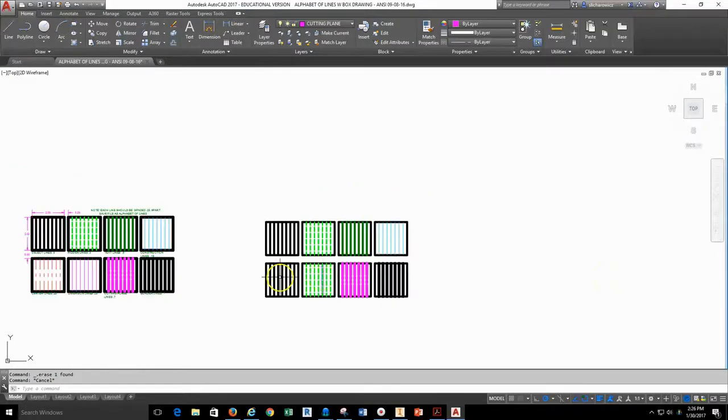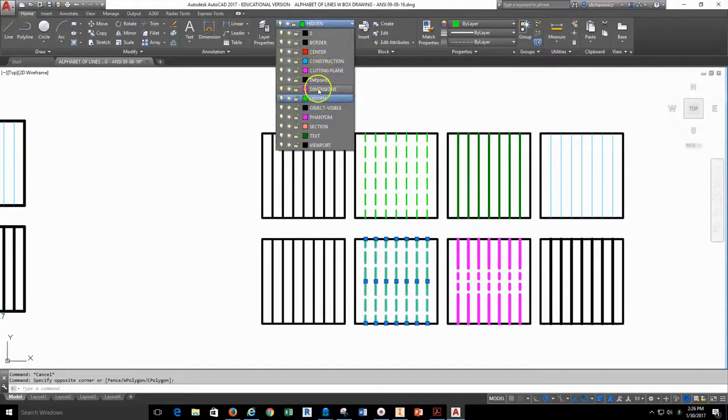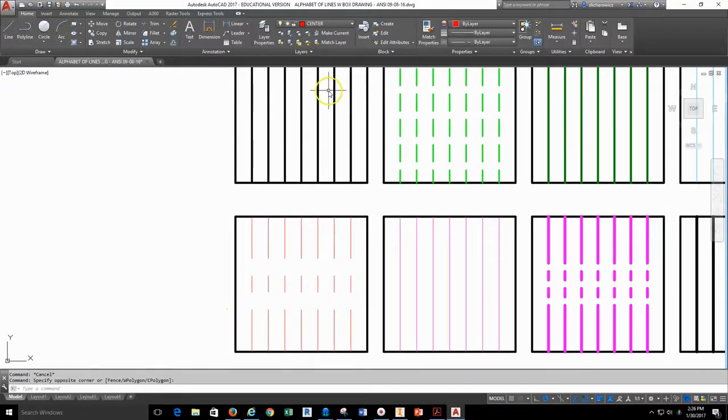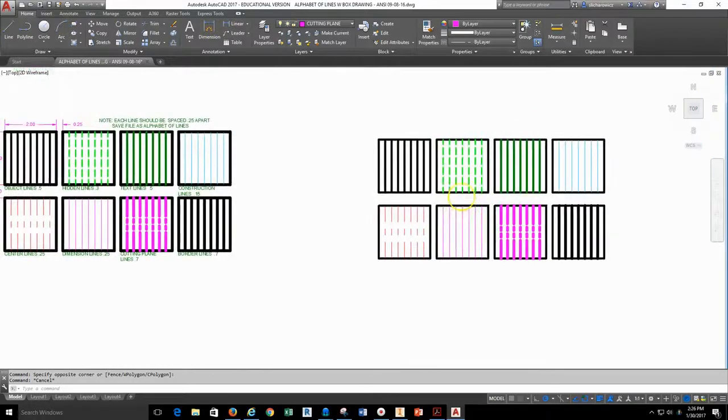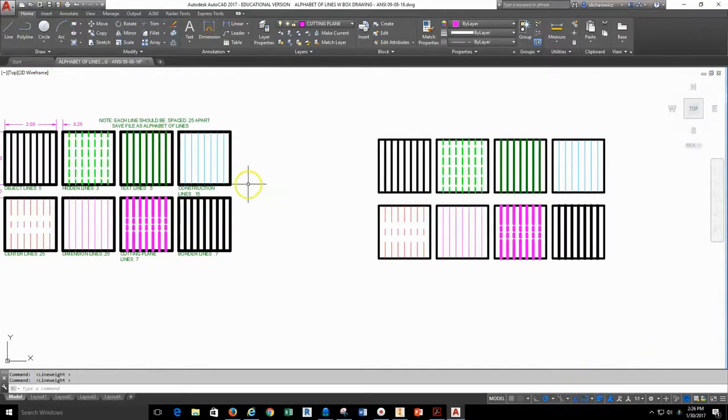As I continue back across here, I'll go ahead and set up the dimension line layer by selecting the hidden lines here, and turning them into the dimension lines. And then, of course, the last set will be the center lines, selecting center lines and then setting them up to be center lines. Being able to turn on line weights to ensure that you are on the proper layer